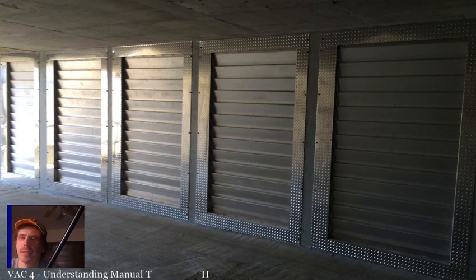So, the test. Questions on your test. First one, you want to make sure you understand what happens in that sequence, right? You want to make sure you understand the sequence of operation. So what happens when the pilot flame is proven on a furnace that uses spark ignition to light the pilot?